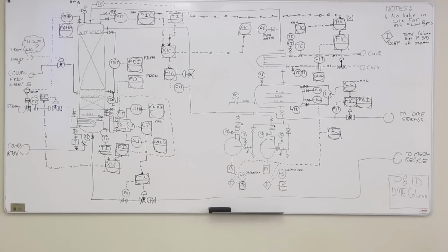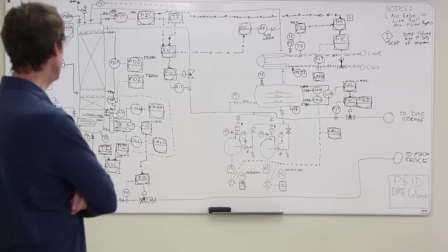Because it's mostly methanol in this process, I wouldn't worry so much about stuff freezing. So only the cooling water. And that's actually another reason why an air cooler might be a good application here. You wouldn't have any electric tracing.